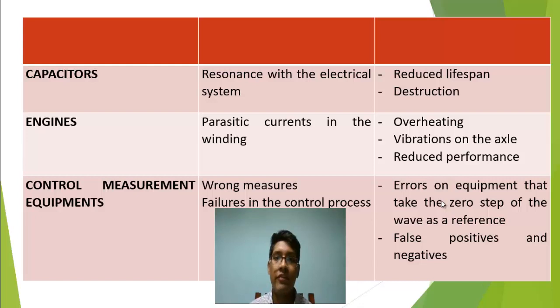The paired currents, such as the 5th and 7th harmonic, have the potential to produce mechanical oscillation in the turbine generator combination or in the load system. This results in torque oscillations caused by an interaction between the harmonic current and the fundamental frequency magnetic field.